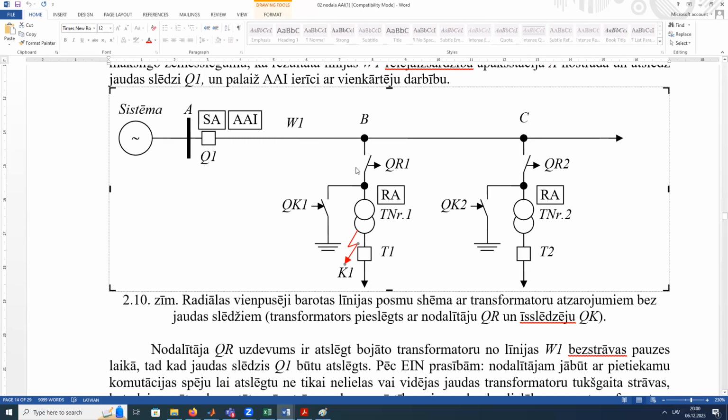What to do? This relay protection, an ordinary relay protection for a transformer, detects this current value and sends a command to this special device, an artificial air connection. So we have a metal piece that, on command of this relay protection, connects this to the ground. So we make by ourselves an earth fault. Here you could see. Why?